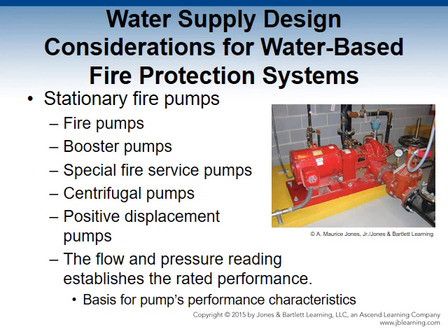There are different categories of stationary fire pumps. In the past, pumps fell into three categories: fire pumps, booster pumps, or special fire service pumps. The distinction was whether the water source was under pressure or whether the pump generated all of the pressure. Today, the term fire pump describes any of the different pump categories. Installation requirements are pretty much the same for each category of the pump. Certain pumps categorized as fire pumps are technically booster pumps.